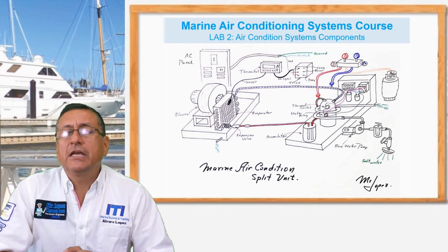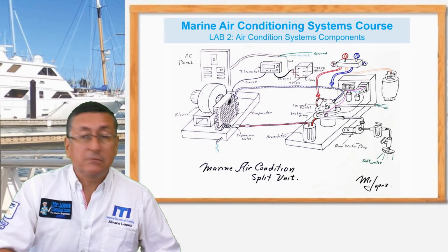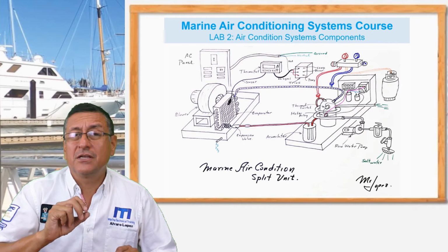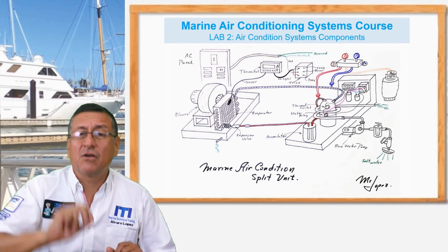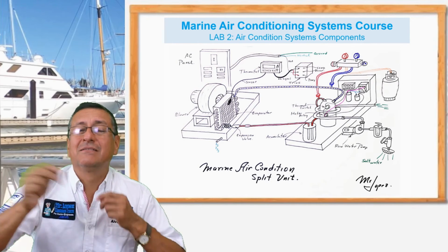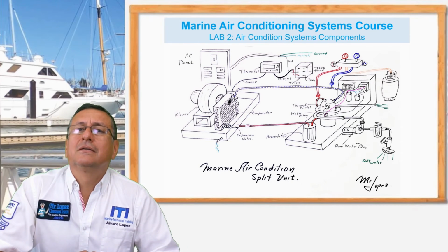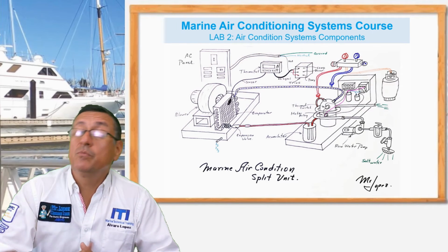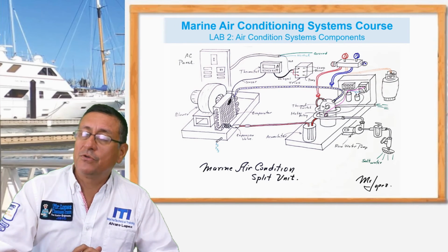Another common problem is, I hear that the compressor starts, but works one minute and stops. Once again, 30 seconds off and starts again. 30 seconds off and starts again. It is cycling. This is an indication that the level of refrigerant is low, or humidity. What is the procedure to verify that?